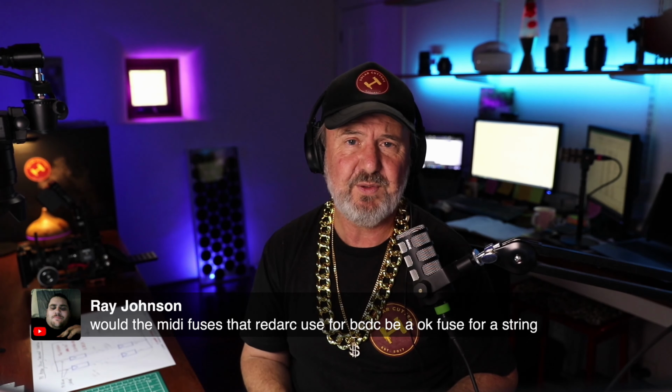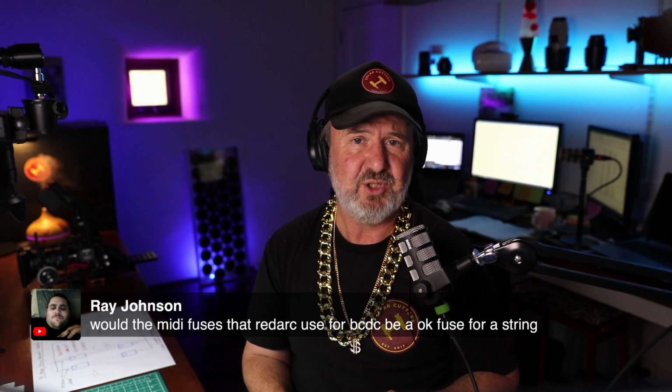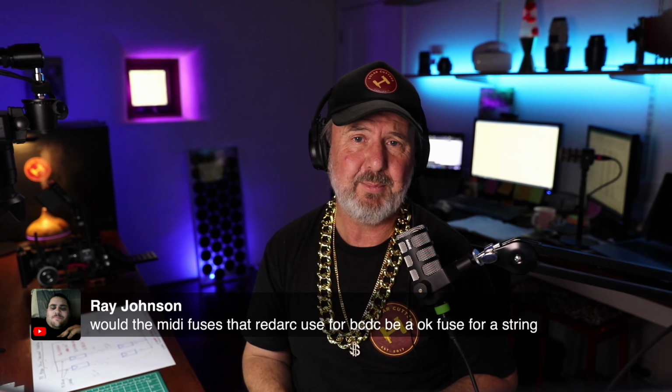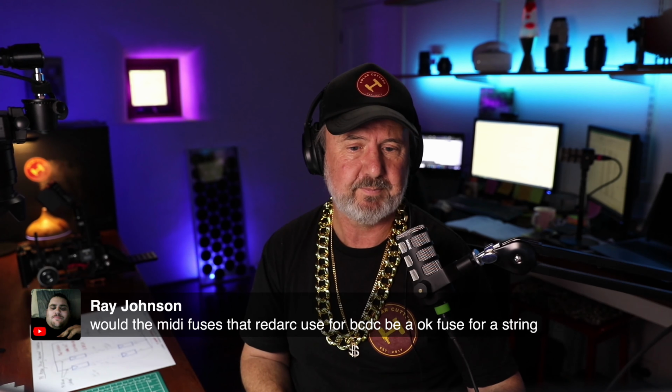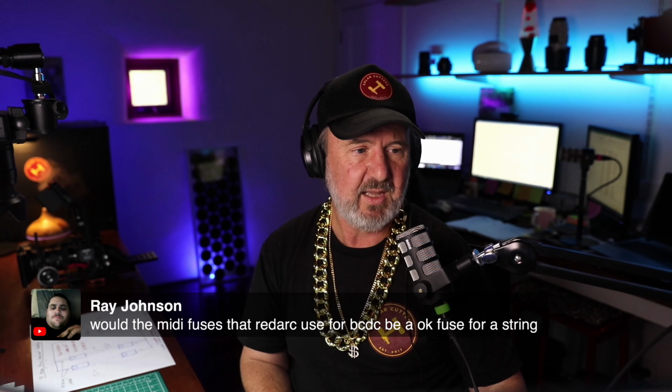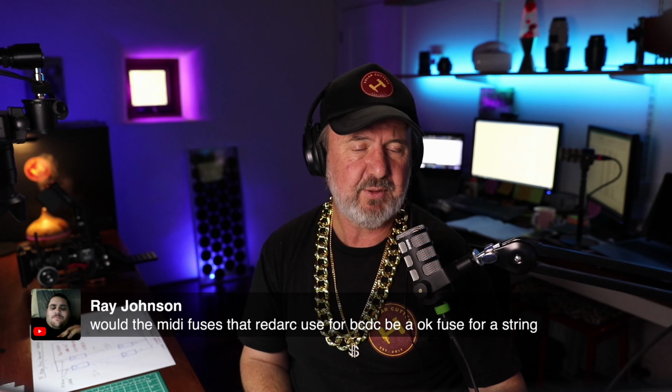And if the fuse type is GPV, suitable for PV applications, then yes, Ray, I think that will be fine. MIDI inline, okay, I'm not quite familiar with the product, Ray, so I'll just leave it at that. It sounds like it's probably okay, but you should always check the ratings that they're suitable for both the voltage and the trip characteristic of solar.